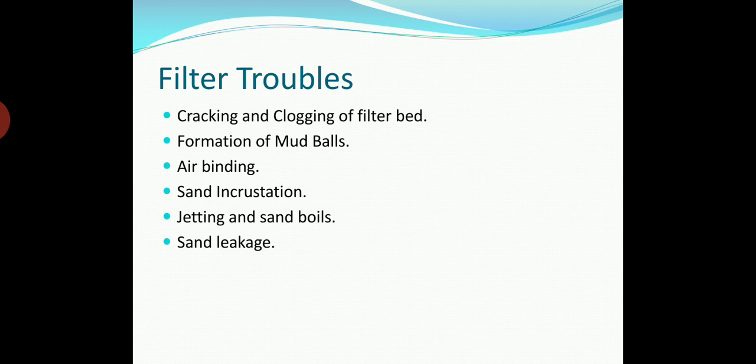Due to this, the sand grains enlarge and the effective size of sand is changed. This can be minimized by carbonating the influent, thereby dissolving both calcium carbonate and any manganese that might have deposited on sand grains. Sodium hexametaphosphate may also be used in small plants to keep calcium carbonate in a dissolved state.